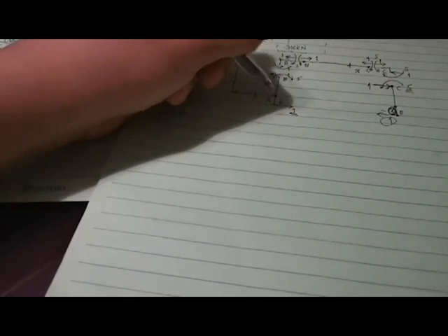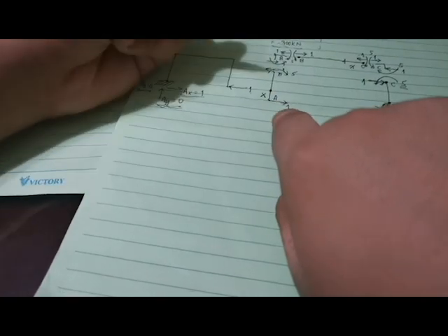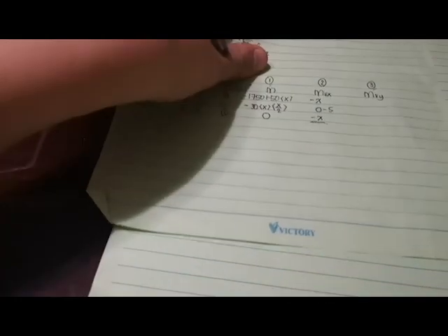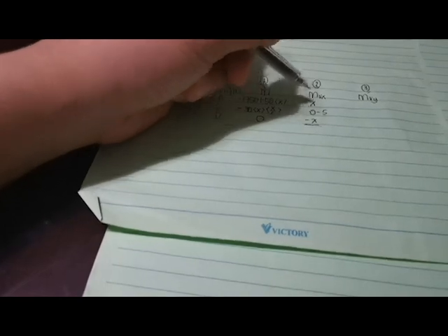Okay, next, our member AB. Your X will be measured from point A, and we only have 1 kilonewton load here, a 1 kilonewton reaction. So 1 multiplied by x is equal to x, but the bending causes the beam to frown. It makes your beam frown, so therefore your MVX now will become negative x. So now we're almost complete.